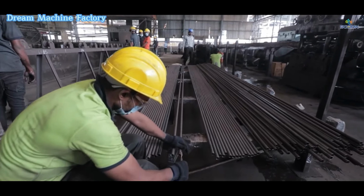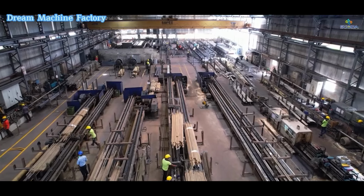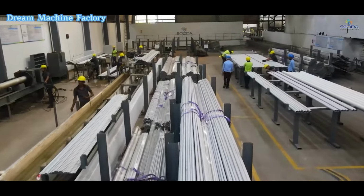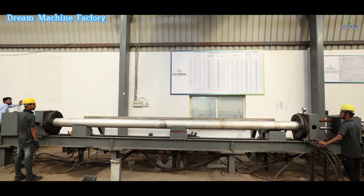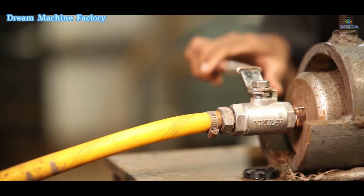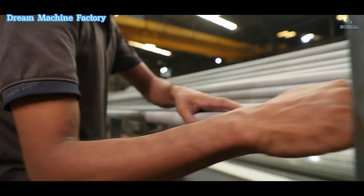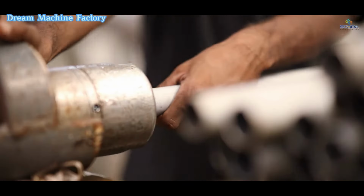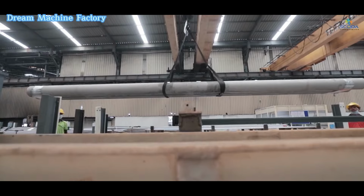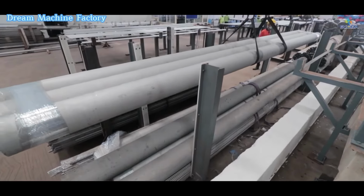The quality control process of seamless steel pipes includes several stages: visual inspection for surface defects, dimensional checks for accuracy, and non-destructive testing (NDT), like ultrasonic or eddy current testing to detect internal flaws. Additionally, mechanical tests such as tensile, hardness, and impact testing are performed to ensure strength and durability.